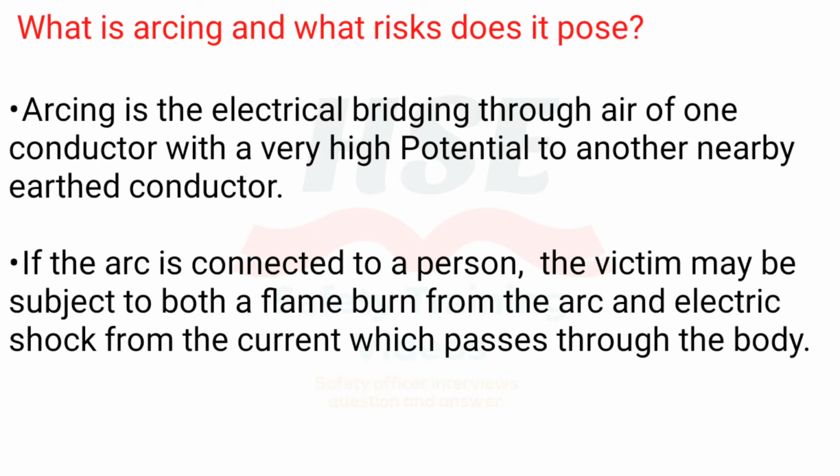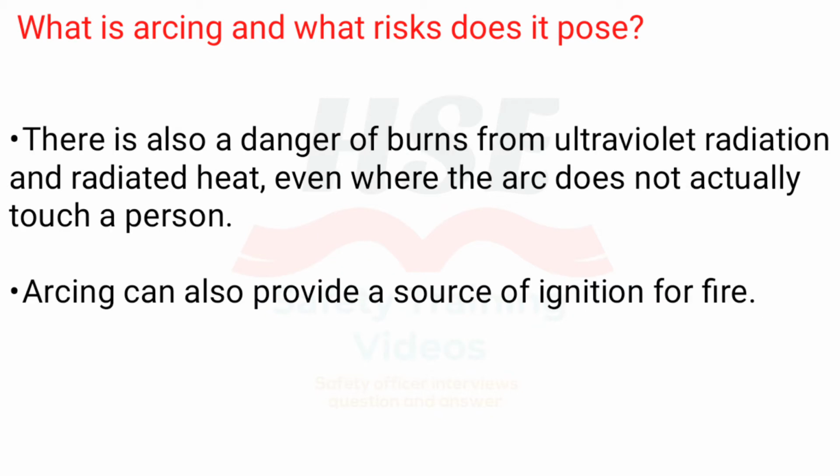flame burn from the arc and electric shock from the current which passes through the body. There is also a danger of burns from ultraviolet radiation and radiated heat, even where the arc does not actually touch a person. Arcing can also provide a source of ignition for fire.